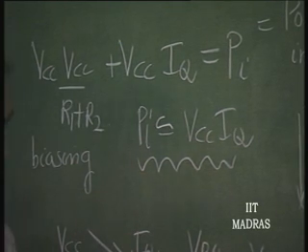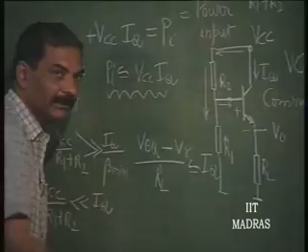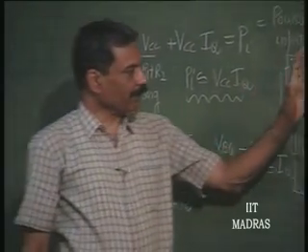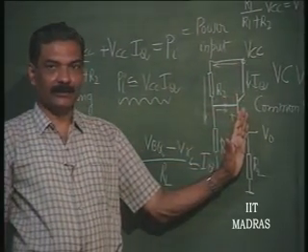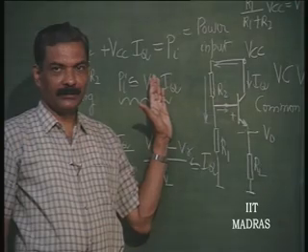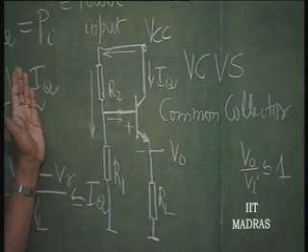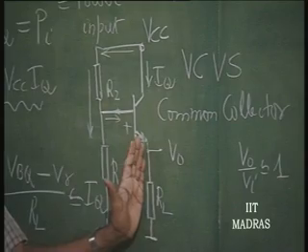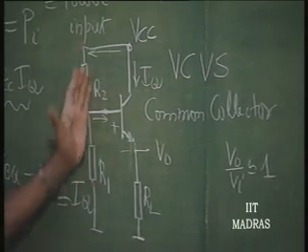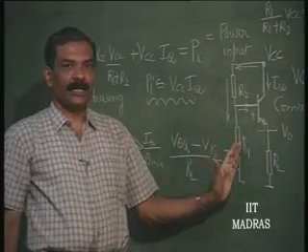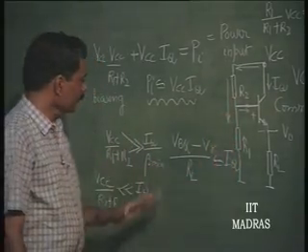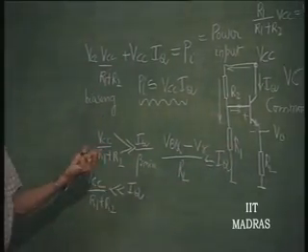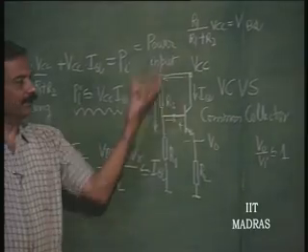This is an illustration of how any power stage has to be designed. If the power transistor is operating at IQ, rest of the current that is drawn for biasing purposes should be much less than that current, okay, and the corresponding resistance etc. are chosen in that manner. So, this gives an idea as to how this power stage is now designed.